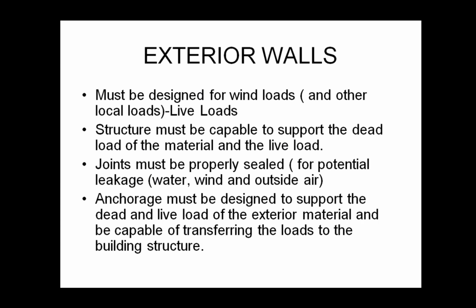The structure itself must be capable of holding the dead load of the material and the live load. Okay, same as any other structure. But with the exterior walls, what we're looking at is that we're adding weight, all right, and depending on the connections and how those walls are supported, your structure has to be designed to take that as well as part of the dead load.